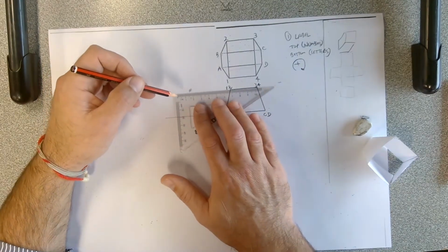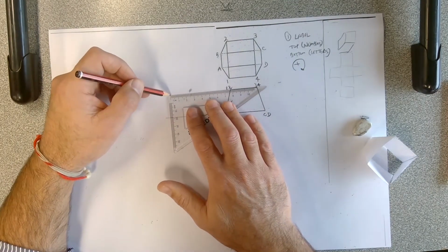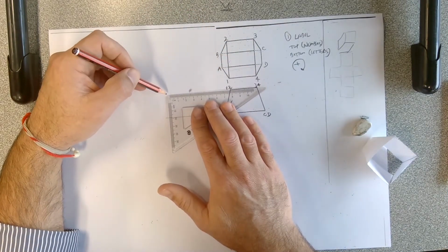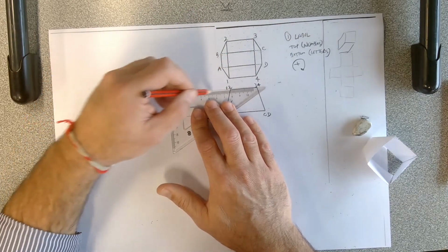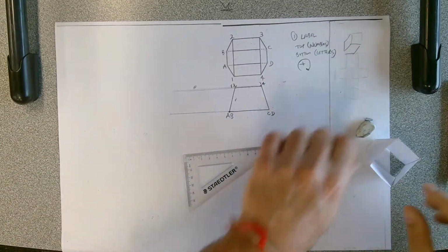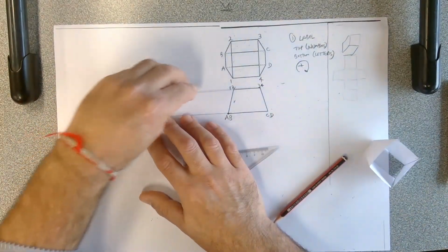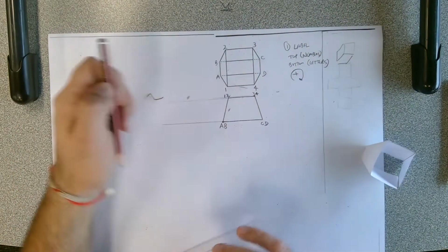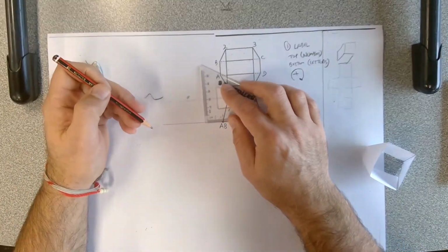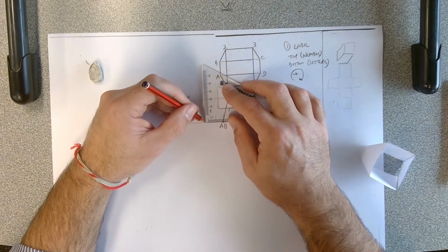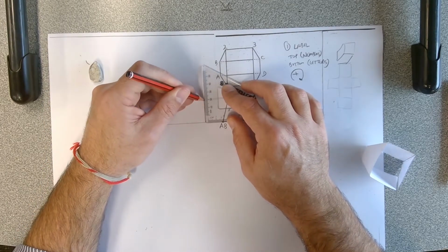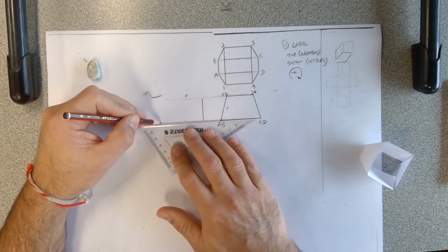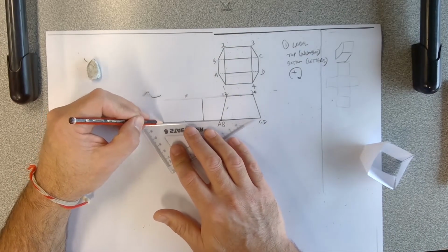Then we transfer a line top and bottom from this front view, and just try and get it as accurate as you can. Don't do it like I just did. Nowhere near right. So once you've done that, we need to get a right angle, because this is how we're going to work out lengths that we don't know. We're going to use this area here to calculate the line lengths that we don't know.